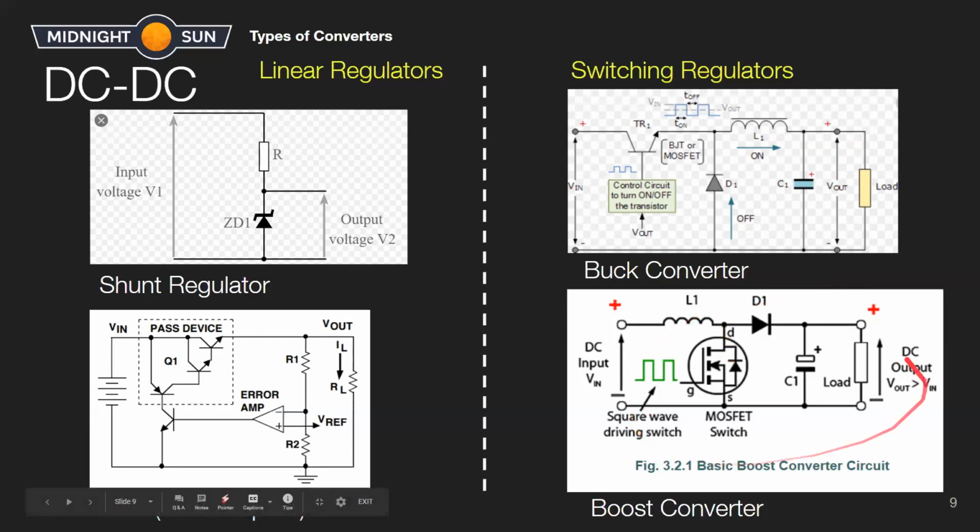And then we come to the boost converter, and it's special because there's no other converter that really gives you a higher reference on the output than the input. But the way that these work is that they turn on this transistor, they charge the inductor, right? And so when this transistor is on, they're just charging the inductor.